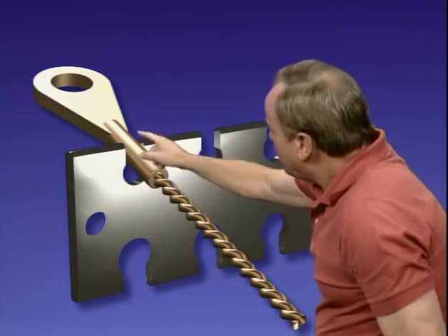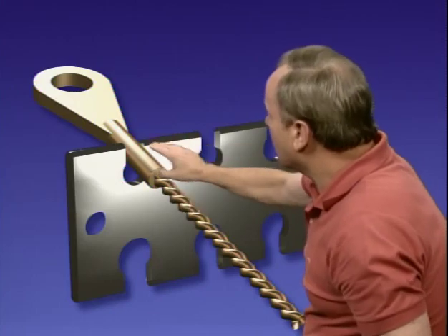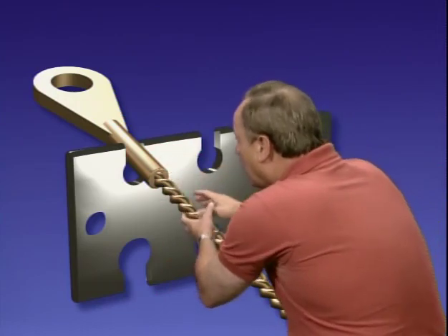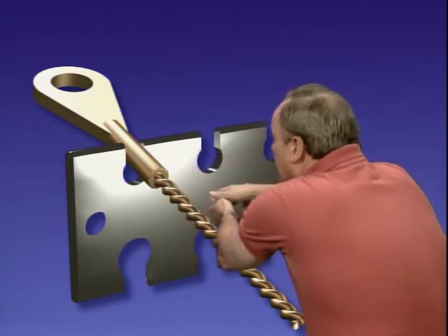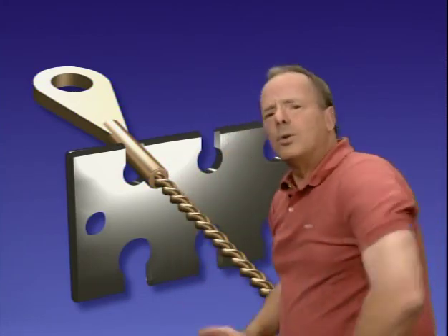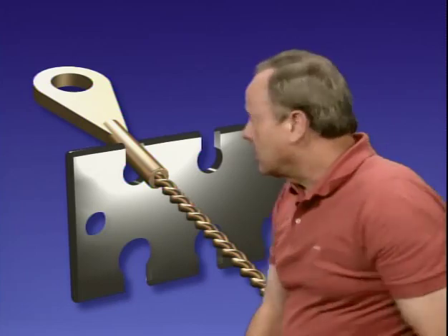Now, when you put this thing together, you want to make sure it lasts. Well, corrosion treatment, it's a good idea. It's not required, but that's one of the things you can do. But the real thing you're concerned about is, is it strong enough? Well, one of the things you can do is what is called pull or load testing to 60% of its breaking strength. And that's required, but that still doesn't show you that you met the manufacturer's requirements for swaging it on. Well, one way to determine that is just this.